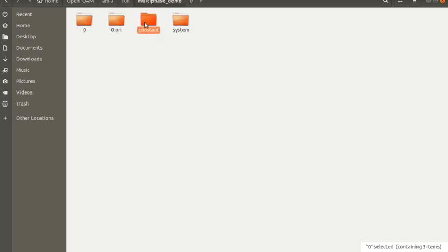And in this constant directory, we can see the triSurface folder, in which we have stored the OBJ object exported from Blender. Based on this mesh, we will create the finite volume mesh by using the blockMesh command and the snappyHexMesh command.